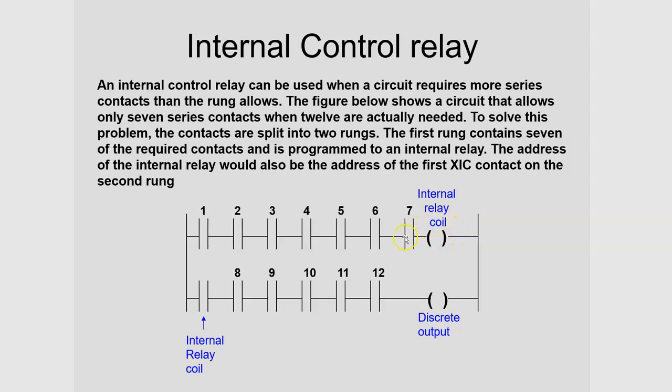And normally, under normal circumstances, this would connect to or be mapped to the output module, which has some device, maybe a lamp or motor, connected to a certain screw terminal. And if you have a set of truths from left to right all the way over to that final instruction, then it'll be true. Just one false, since these are all ANDed, and this will be false. But here, this internal relay coil doesn't reference anything outside of the PLC.